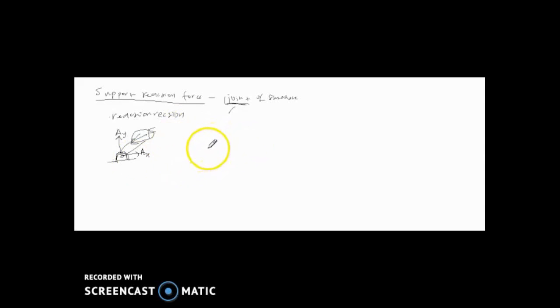Normally we have a joint like, for example, this one, some kind of spring here. This is one sort of support or joint also. If the normal force is this way, then to prevent the normal force, your reaction force will be in that way. So simply, your reaction force will be like this.